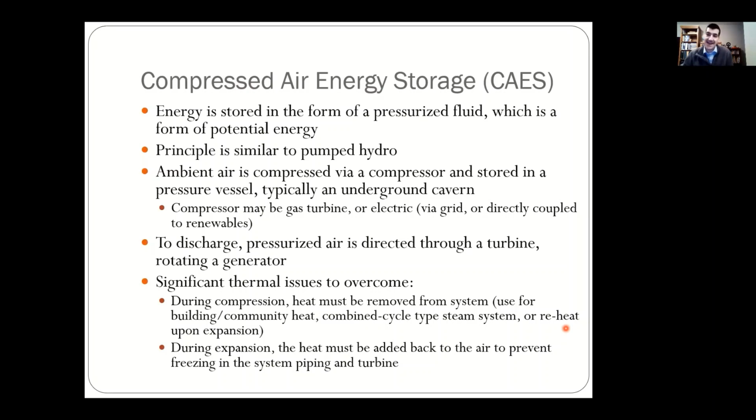So you have to add heat to the air as you're expanding that gas. If you can store heat somehow to reheat it on expansion, then you can just use that. Otherwise, you have to use some type of boiler or electric heat or something to actually add thermal energy to the system upon expansion. So that's a drawback.